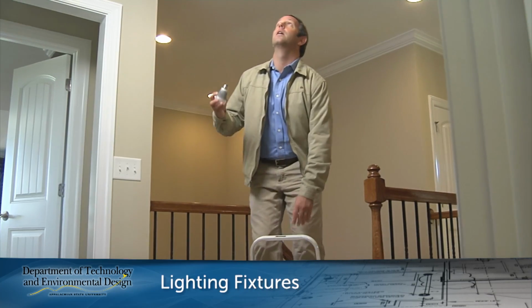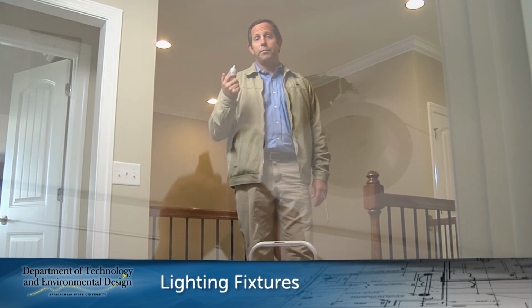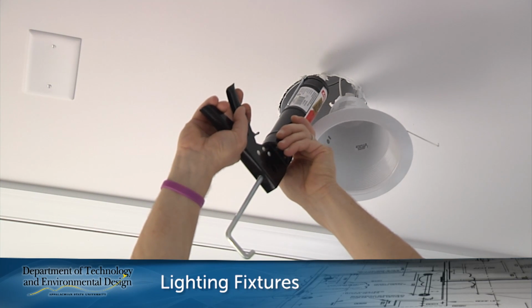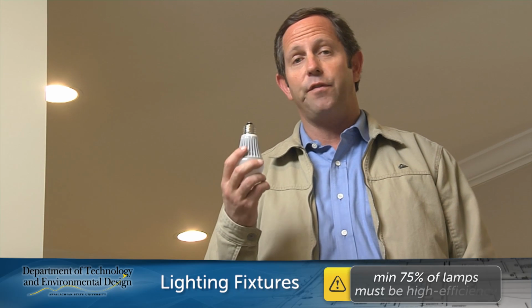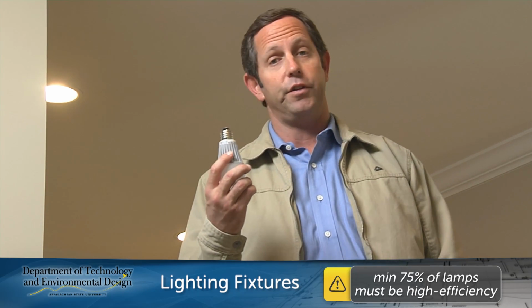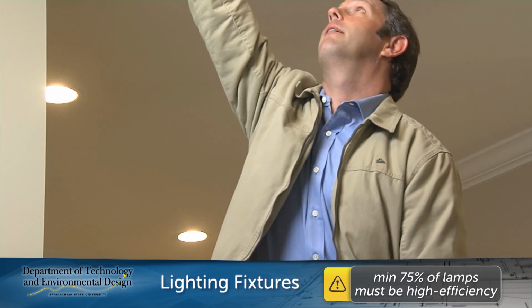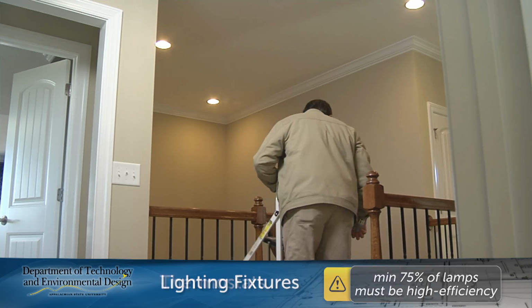Now I'm going to go over a couple quick points on lighting fixtures. When recessed lighting fixtures are used in the thermal envelope, they must be sealed with a gasket or caulk between the housing and the ceiling covering. And a minimum of 75% of the lamps in permanently installed lighting fixtures must be high-efficiency lamps. There, that'll save some energy and some money.